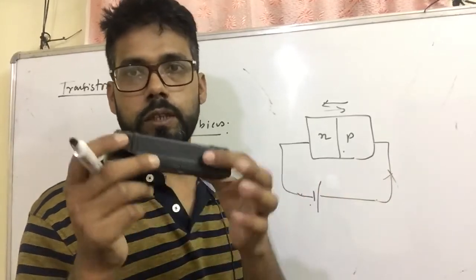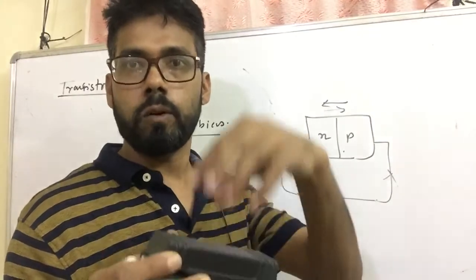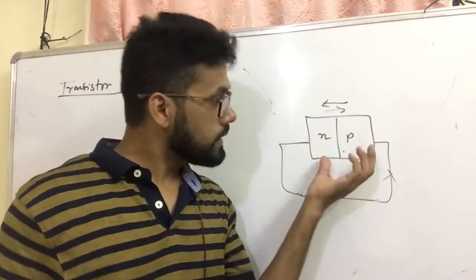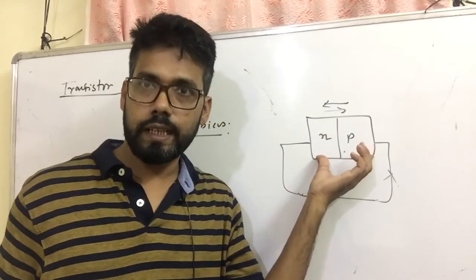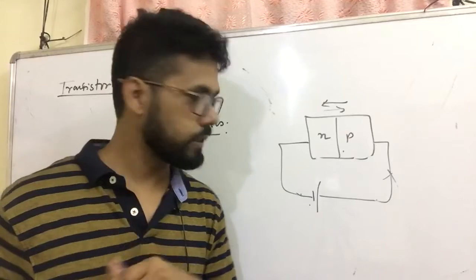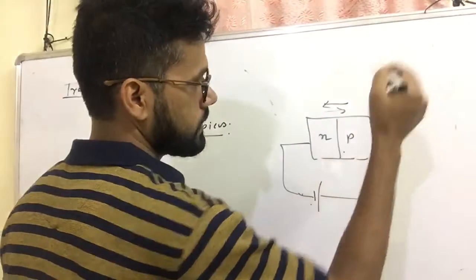I mean, suppose you put an emitter, you will measure the current. But that current is only because of electrons, not because of holes. Clear? Okay. Then inside this portion, the hole current exists. Outside the semiconductor, there is no concept of hole current. Okay. Now what is the forward? Now I am getting the output current. This is the output current.